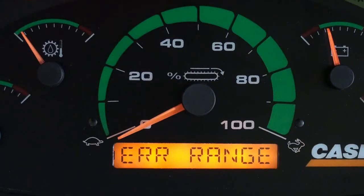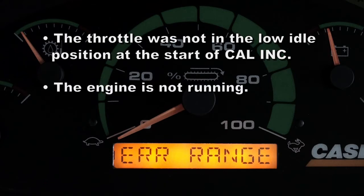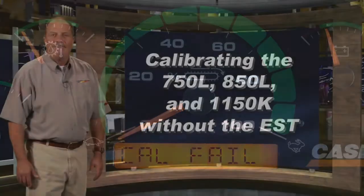If the instrument cluster reads Error Range during this operation, the throttle was not in the low idle position at the start of Cal Increase, the engine is not running, or no engine speed signal is being received. If at any time during calibration the instrument cluster reads Cal Fail, stop the engine and restart the procedure.